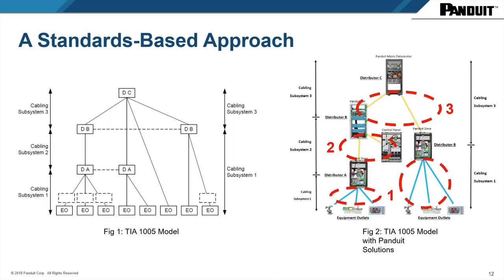Now, what we call the last mile in a network is where a zone controller is connected to the edge devices. All the cabling that's run between those systems is generally copper. So why do we run copper at the edge devices versus fiber? Copper connectivity is sturdier, and there are a lot of connectivity solutions that you find being sold in the industry that are copper connections. You will not find many companies delivering fiber connectivity to the edge devices. Generally, the connection between an edge device and a zone enclosure is under 100 meters. Therefore, you could use copper.